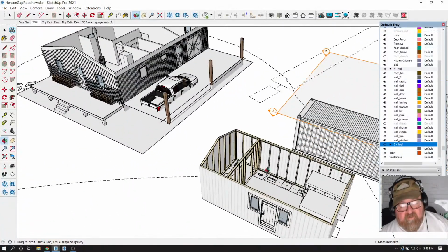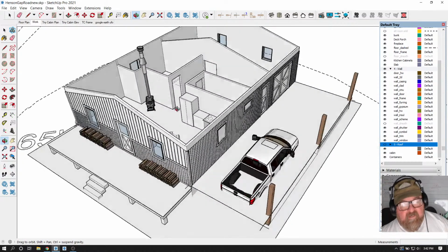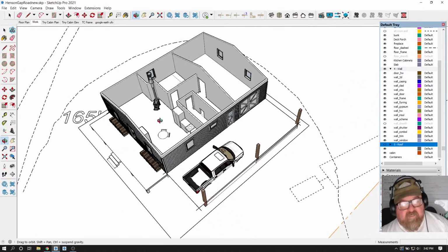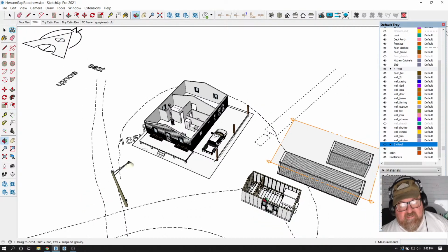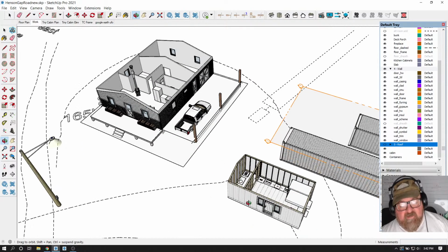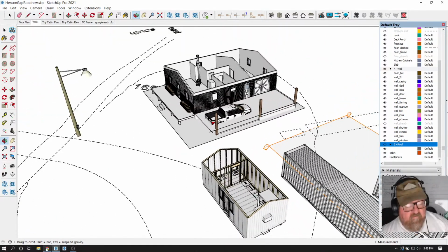I'm going to have 100 amps here to begin with, and I'll probably leave 60 out here, and then I'll have the rest of it. That way I'll have enough for all three spaces: the shop, this living area, and this to maintain. I won't need that 100 amps out here when I move into here. I'm obviously not going to change the breaker panel out.